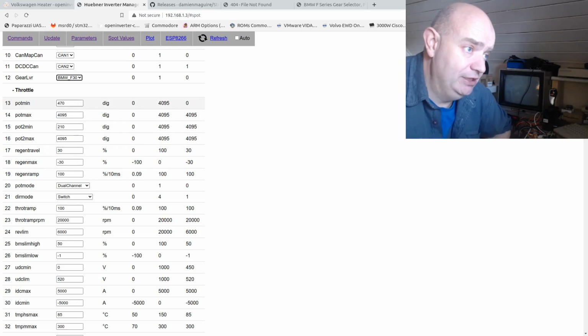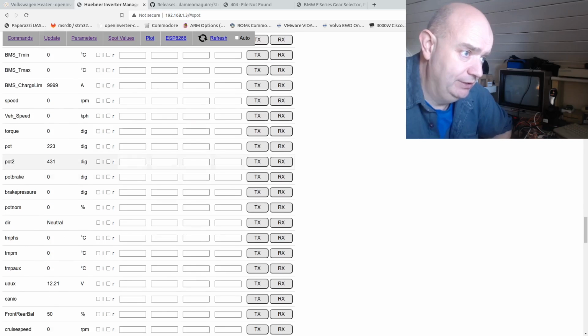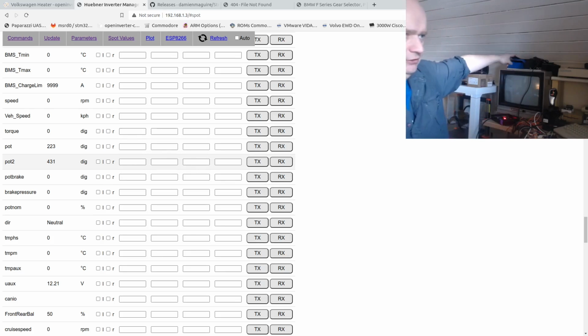And so you've got two channels. You've got pot and you've got pot 2. And you've got the raw digital values here. If you come down to spot values and we go down to pot, you'll see what they currently are here. So see at the minute pot is at, so this is channel 1, this is channel 2. Pot's at 223 and pot 2 is at 431 with the throttle. It's just sitting up on the monitor there.